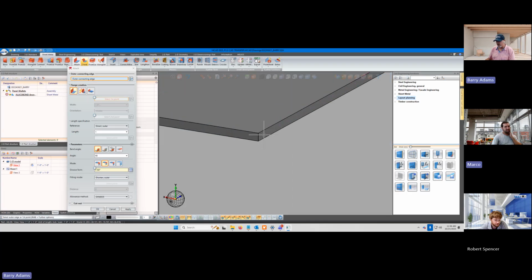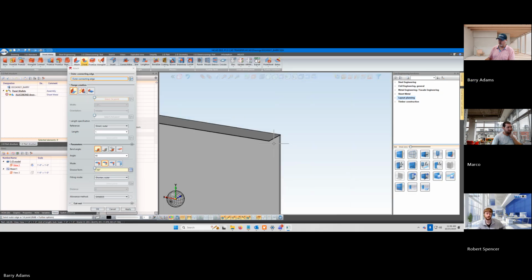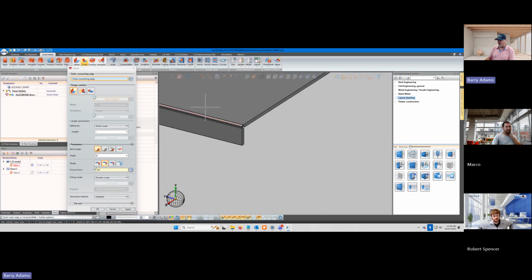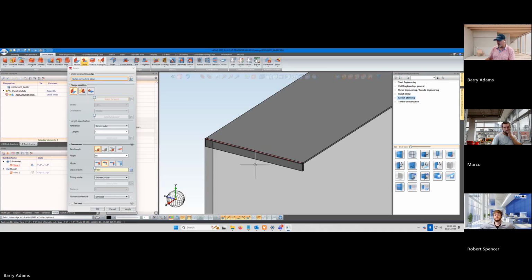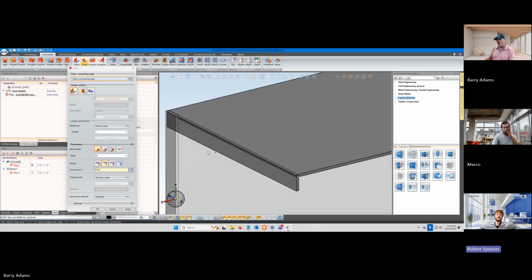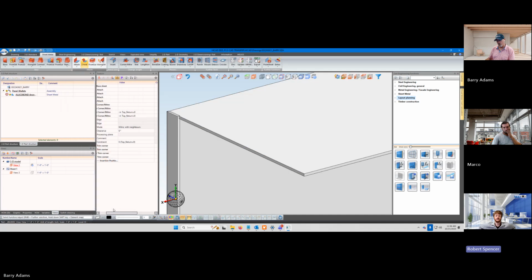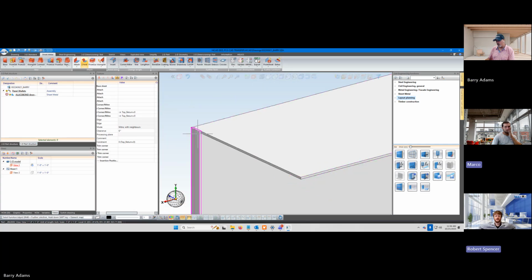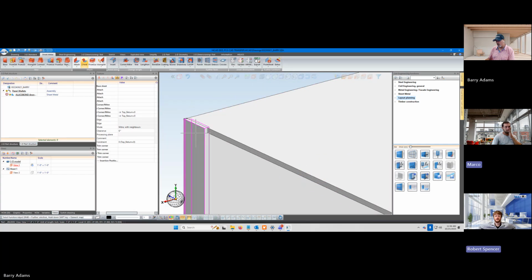So this one also has that correct edge. Yeah. One of my flanges, I need to make this edge just like that other edge. Let's cancel the feature here. I want to look at the edge here before we add the flange. Okay, you see how the, right here. My thought is, let's look at the fitting mode of the flange next to it. So let's look at that feature step, because your fitting modes kind of all need to sync up.